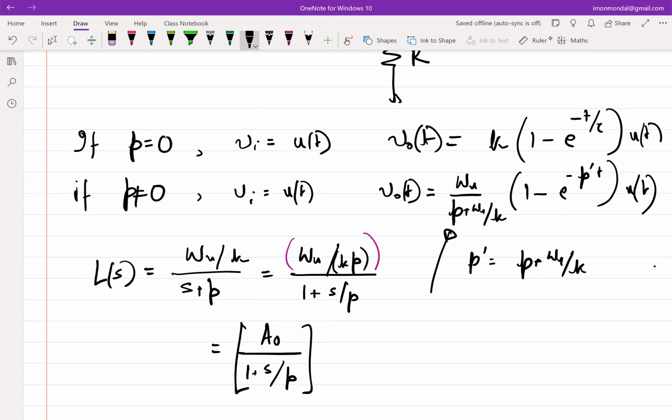So now let's look at the same thing. One of the important takeaways from this argument, of how to ease your algebra, is that if you are not bothered about the steady state error, you can ignore P. So let me write it down also. If we are not concerned about steady state error, this will ease your life, your algebra, quite a bit. You don't have to carry around some pesky terms which are essentially not giving too much value. But obviously, if I ask you to figure out what is the steady state error, then you cannot ignore P.